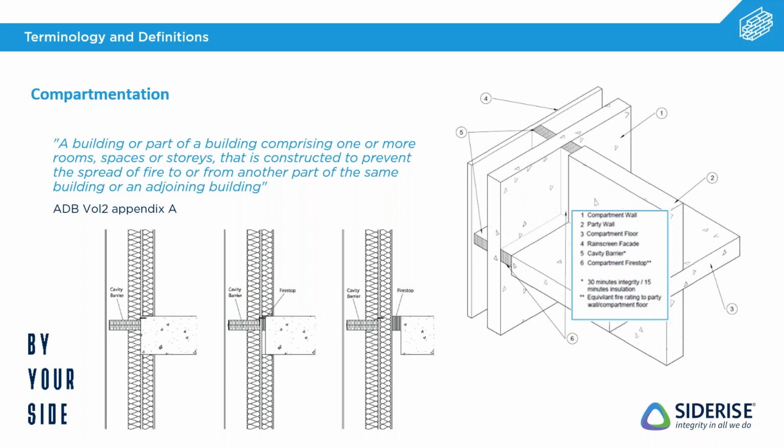And that would then give you an idea that you should have whatever fire rating has been required for that project. It'll take that long before the fire can then spread to the adjoining rooms or compartments, and then again repeat for the next spread. On the outside of the building or the facade, it's still important to try and maintain this compartmentation. As I mentioned before, otherwise that facade could enable the fire to spread past or beyond that compartmentation within the building, and then actually bypassing fire measures and spreading far quicker.